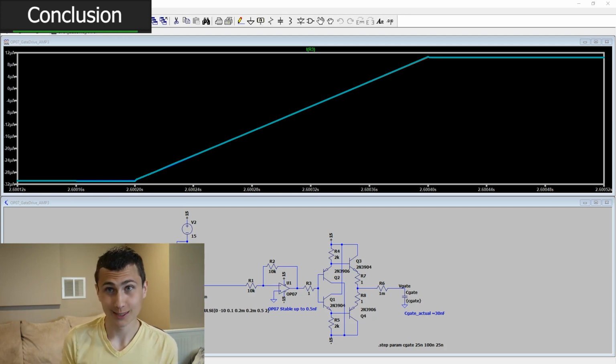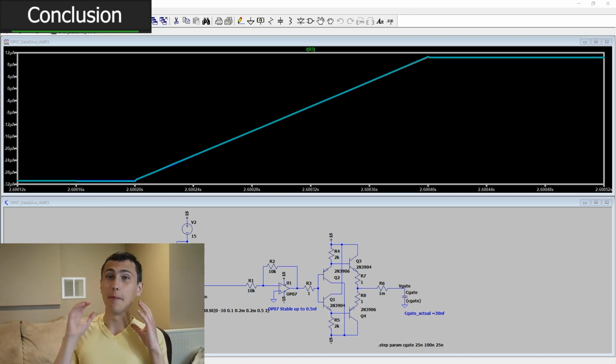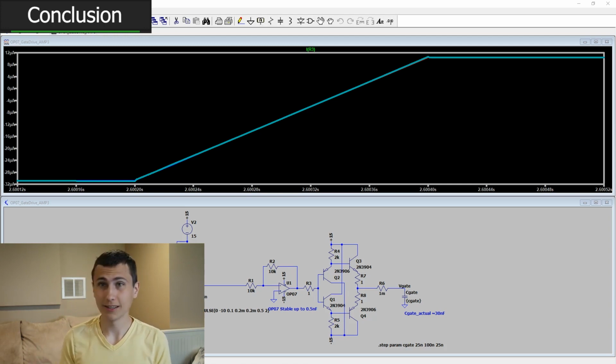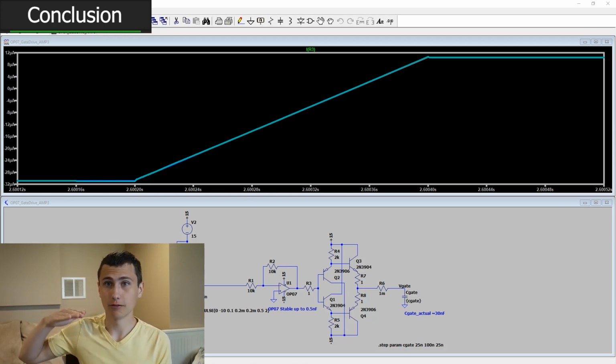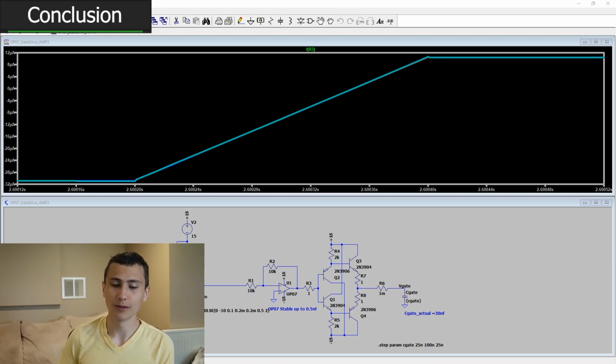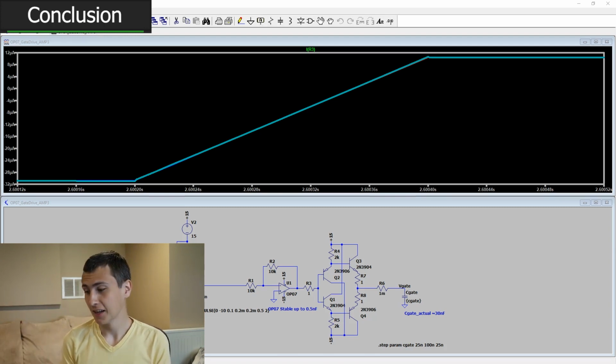I don't even think it'll really slow it down. Our compensator is basically built for this DC offset, right? There's a DC offset that will be the operating point of our FET, and that's going to be like 4 or 5 volts, and we can account for that just fine. What's another 100 millivolts? I think it's fantastic. Rarely have I had an opportunity to design a BJT buffer into a circuit like this and actually have a justification for it. So I am excited to do something that's just a little weird, and I think it'll work out just fine. That's fantastic.